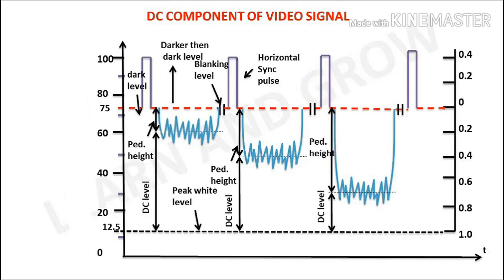The vertical alignment pulse, a jagged pulse forcing the vertical deflection circuit to initiate flyback, generally will not start with the start of vertical alignment, because the alignment pulse must build charge in a capacitor to drive the alignment circuits.